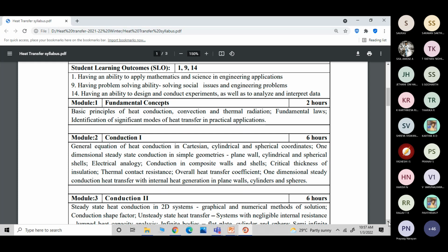Because usually the boiling point of water at atmospheric pressure is 100 degrees C, and for high pressure steam it will be around 300 or 400 degrees C, with a maximum critical temperature of 374 degrees C. So if the steam flows at a high temperature inside the tube and is exposed to the surrounding atmosphere, which is at 20 or 30 degrees, then naturally heat transfer takes place from the high temperature body to the low temperature body.